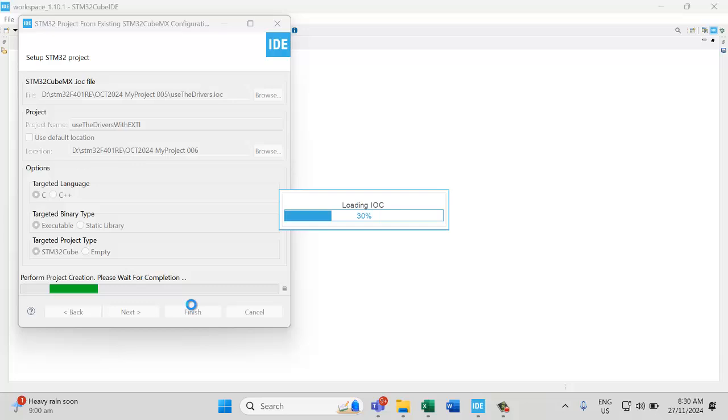So first thing first, we need to modify the IOC at the push button or switch for pin PA1, PA4, and PB0.